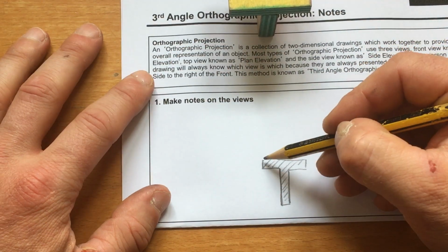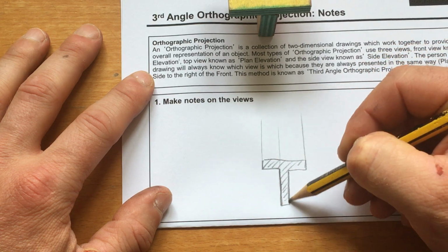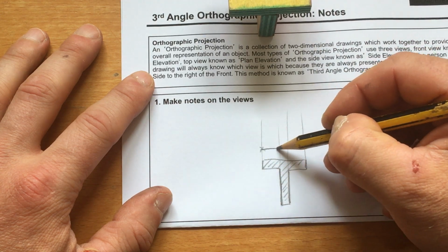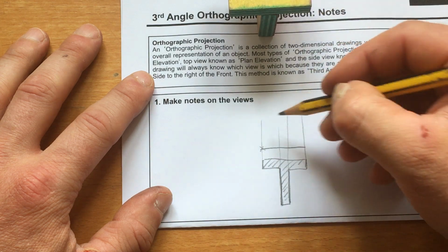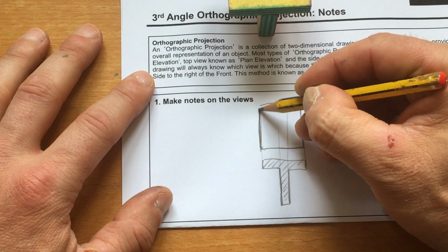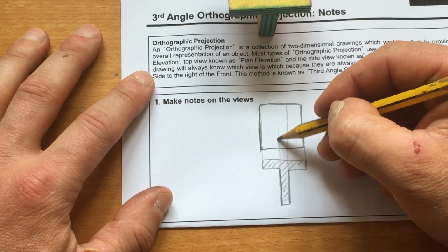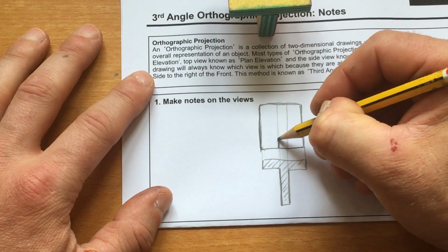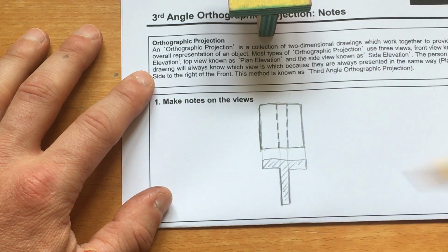Now we do that by projecting up all of the vertical lines that we've got connected with this drawing here. We decide where we'd like the plan view to be, and then we can mark this line here, which represents the edge of that object. We clearly measure this bit, and then we draw in that view on the side, and this would represent the plan view, what we can see. Now those two vertical lines that came from the stem of the letter T, we can't see them from the top here, so we mark them as something called hidden detail on the object here, which we'll come to in a bit in the video.